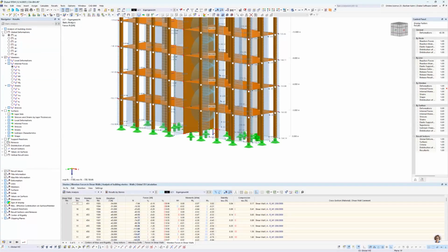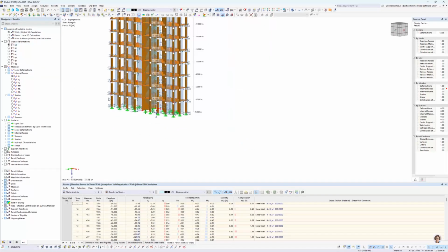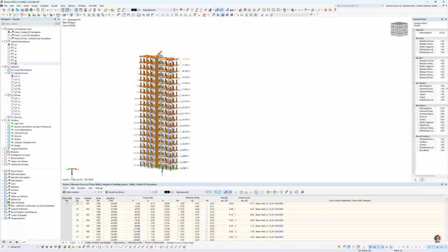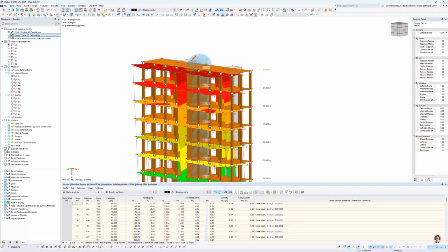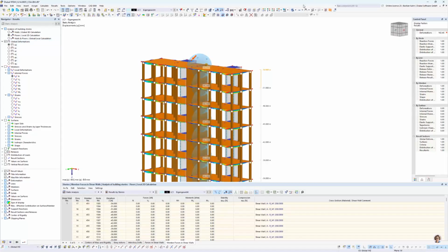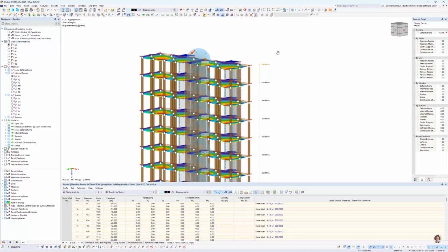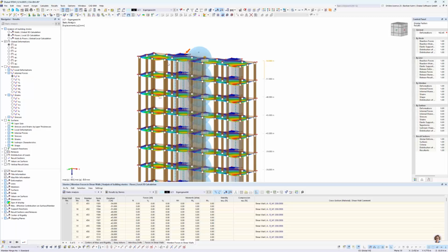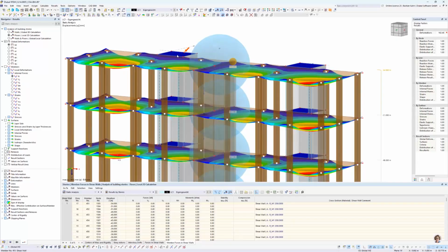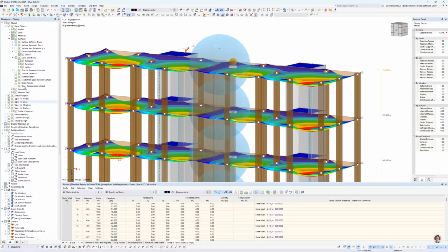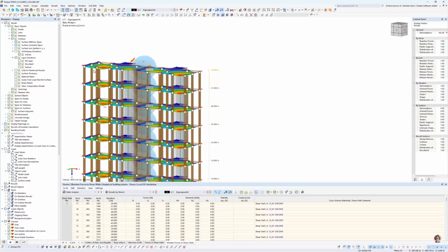So now that we've calculated it, we have here analysis of a building story, and we have here global deformation for the walls, that's not so fancy, I would like to say. But here you see that in here for floors, it's only calculating the horizontal elements. So that's this concrete surface and the CLT. The columns here are not really existing. They are skipped out of the 3D model.